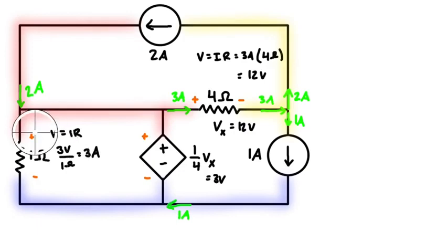And again, this is a resistor. We know the plus side is over here, and the current is going to enter the positive side and go out the negative side. So we can label that our current here is 3 amps going down. That means that there's 3 amps here, and then 3 amps coming into this junction as well. Okay, so now at this junction we have 3 amps coming in plus 1 amp coming in, so we have to have 4 amps coming out. So it's going to be going up like this, and that means that there's 4 amps going in here as well.